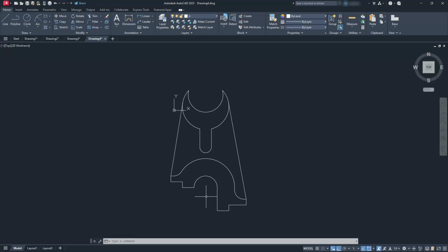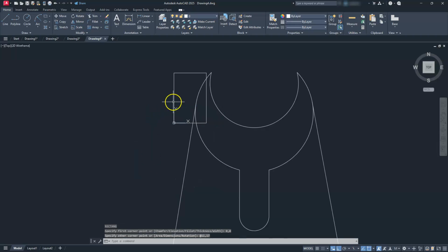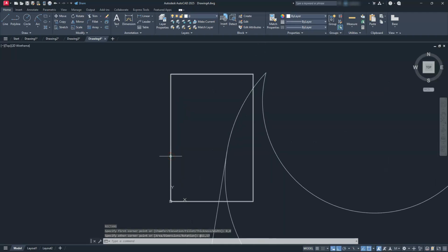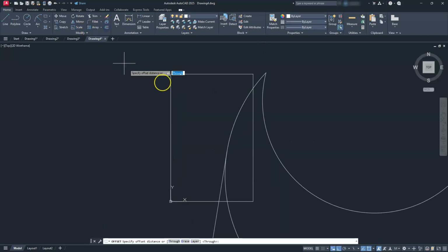Next, let's go ahead and put a title block around this, and I'm going to use this one doing the standard method. So I'm going to use a rectangle, REC, enter. I'm going to type in 0, 0, enter. And we will use a B size. And we're going to make this one also in the portrait mode. So let's make it 11, 17. Okay, let's look at this. Let's do an offset. Give it a distance of 10.